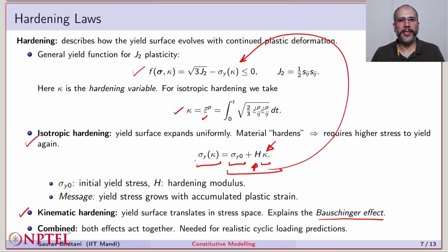So if you think in terms of yield surface, if you were here earlier and if you had the limit for yield stress for tension and compression, now what's happened is that this value has reached here, but this has reached here and it has softened. So it's like the whole surface has translated from the blue region to the green region. So this is what we meant by saying that the yield surface can translate in kinematic hardening. So this has to be dealt with differently.